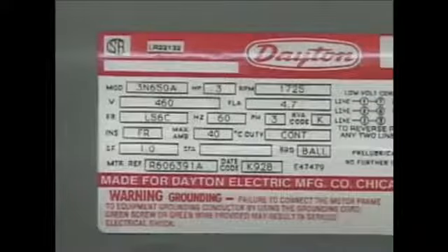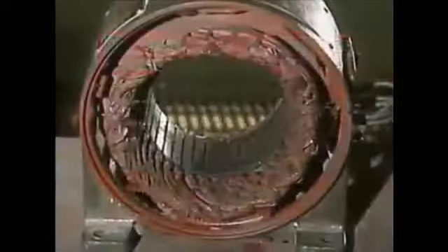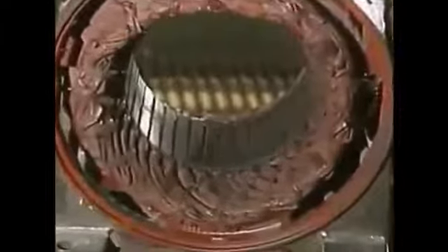Now, in addition to controlling the operation of a motor, motor controllers usually protect the motor as well. For example, motors are rated to deliver a certain amount of power. If demand on the motor increases, current flow through the motor increases. If the current is allowed to exceed the rated capacity, the motor's stator windings could be damaged. In addition, the rotor and possibly other parts could be damaged by excessive current.